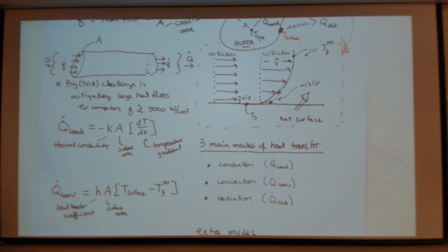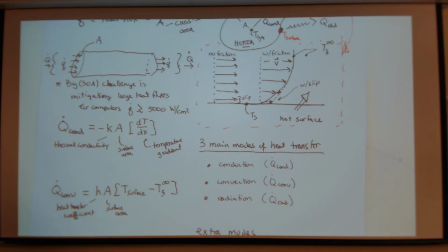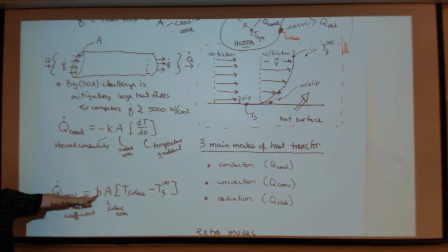The greater the velocity, the greater the coefficient. So when we talk about aerodynamics type things, and when you go to super high speeds, we usually have distinctions between subsonic and supersonic. And if you're taking fluids, you're hearing about the Reynolds number. But nevertheless, the heat transfer coefficient is highly dictated by the density and velocity of the fluid flowing over.